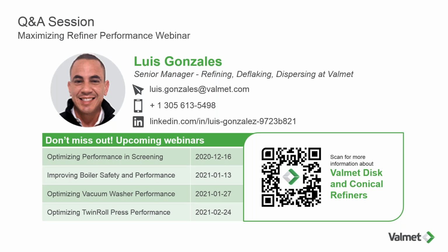So we're looking at analyzing the freeness either before and after the refiner, or before and after each refiner, but most importantly, at the blend chest. If you have multiple fibers going to the blend chest and you're trying to adjust the freeness on each particular stream going out, but then at the blend chest you're changing the ratios, the result at the blend chest is obviously going to be all over the place, because you are adjusting freenesses for each one, but the ratios change.